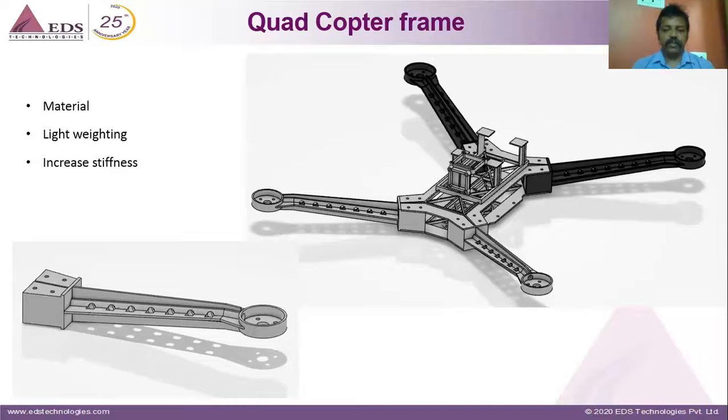So we do a lot of material study. Once we do the material study, we also need to find out how to lightweight. Whenever you do lightweighting, there is a decrease in stiffness, but then we have to bring in other factors which help us in increasing the stiffness, such as adding stiffeners, creating a hole, bringing in some other kind of material, or creating a sandwich of multiple highly stiff materials. There are multiple factors which can help you in increasing the stiffness.